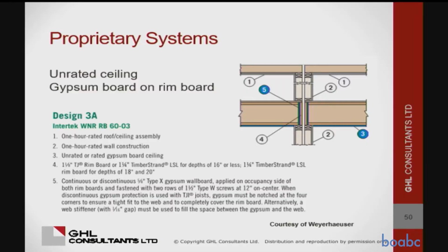Because there are details in the truss joist book where you do put gypsum board on the rim board instead, although I don't know why anybody would want to do that. But I think what they mean is you cut a piece of gypsum board and you paste it against your rim board, and then you put the trusses up against it. But then when you try to do this mid-construction, the structural guy goes, no, you can't put gypsum board behind my joist. I don't have enough bearing.